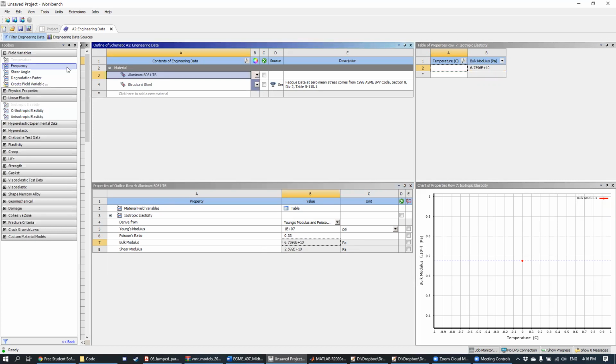And so, just to recap, there's lots of different material properties here that you can specify for your material, but you don't have to specify all of them. And actually, a lot of them are really hard to find for a lot of materials, even if you look at the material data sheet. And so for a static structural simulation, which is what the majority of what we're going to be running in this class, the only thing that you need to add is isotropic elasticity.